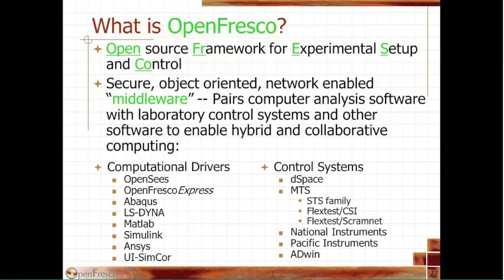So you will need some computational drivers, and you can see what we have in terms of computational drivers. For example, today we're talking about OpenSees. So you need a computational driver, and then OpenFresco as a middleware will allow you to connect your finite element software to the laboratory control systems. In terms of computational drivers, we have OpenSees, and we have OpenFresco Express, which is a graphical user interface that I was showing in an earlier presentation about this same topic a year ago or so, a little less.